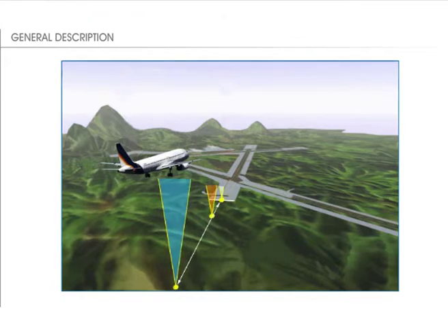The VHF omnidirectional range and marker system is a radio navigation aid, NavAid, which provides aircraft position in comparison with ground stations. A ground station transmits beams, called radials, outward in every direction. A receiver in the aircraft is used to detect these signals, and provide bearing information to airplane systems and instruments, which indicate the position of the airplane relative to the VOR station. Each radial is numbered according to its bearing from the VOR station. The VOR system refers to the magnetic north, and the zero.